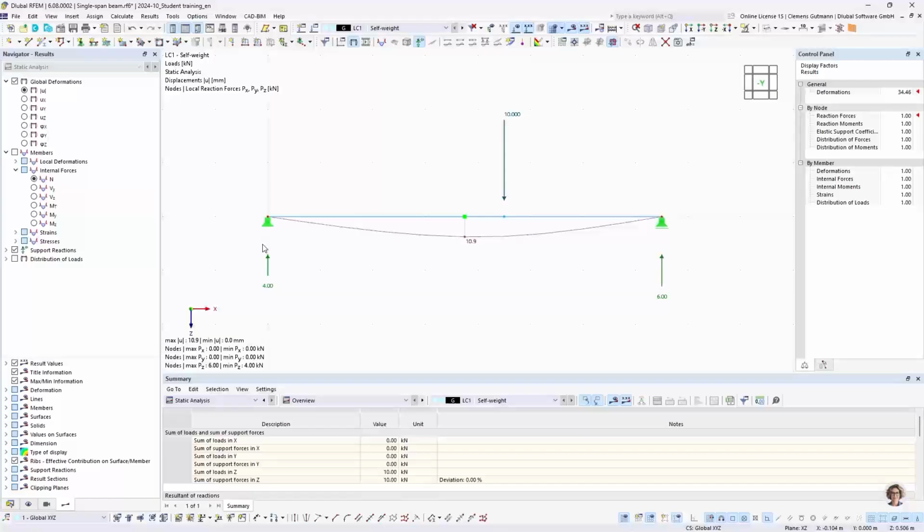because it happens quite often that you make some mistakes, that you overlook something, and to not drag around some mistakes, I recommend you to run a quick plausibility check, and the sum of forces, for example, in the Z direction is a good start for doing that.